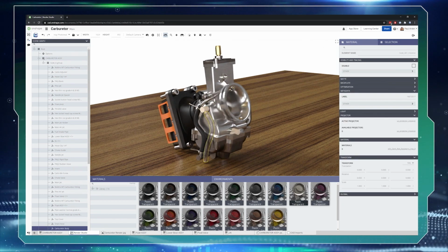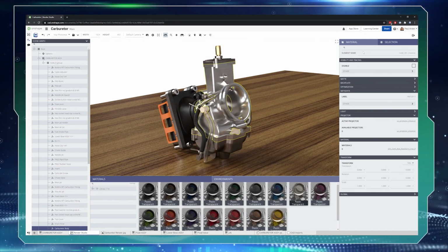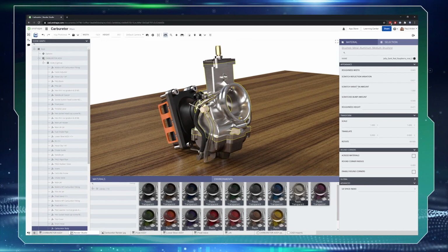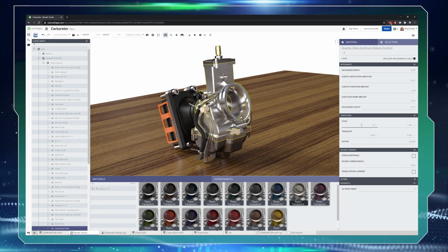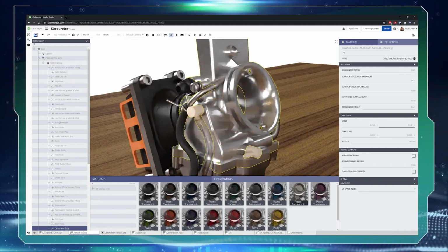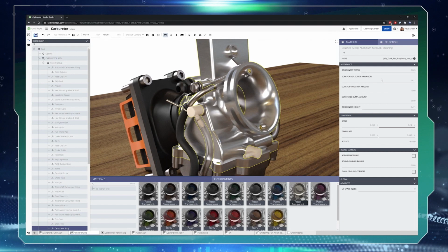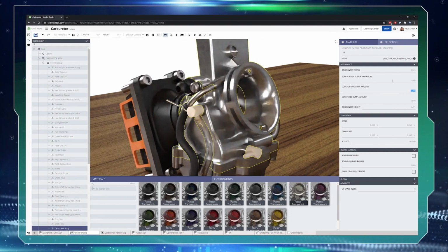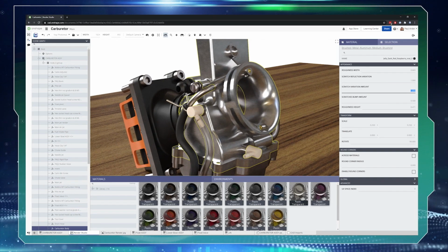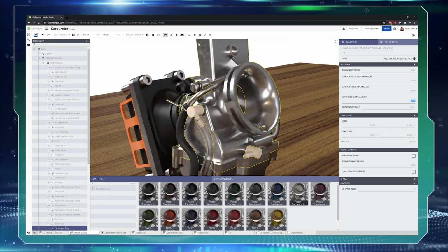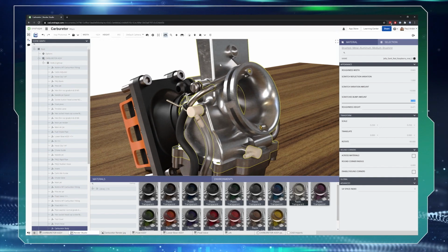If we click the metal, you can see that it's one of our new V-Materials 2 materials with these nice parametric parameters for scratches and reflection, variation, that sort of thing. But the scale looks a bit big on those scratches, so let's make them 1/4 of the size. And let's increase the variation in the reflections just to give the material a more aged look. And to get a bit of imperfection in there, we'll up the variation on the scratches, and you'll see now we can get a nice bit of imperfection showing.